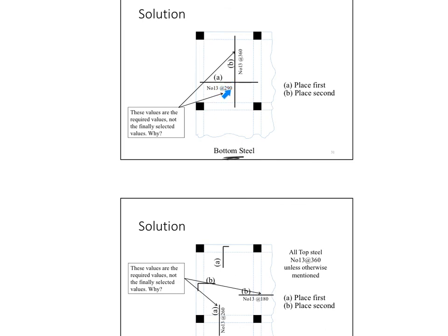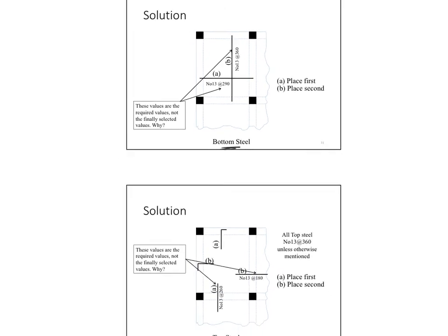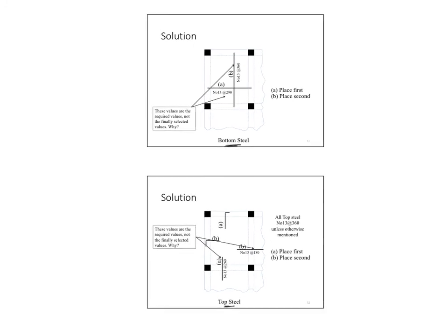Remember that you want to pick a number that construction workers don't get confused with. 29 centimeters between every bar and the next bar is a really inefficient type of spacing that will cause mistakes on the site. So in this case, that 29, for example, comes down to 25 or even 20. That 36 could go down to 30 or even 25.